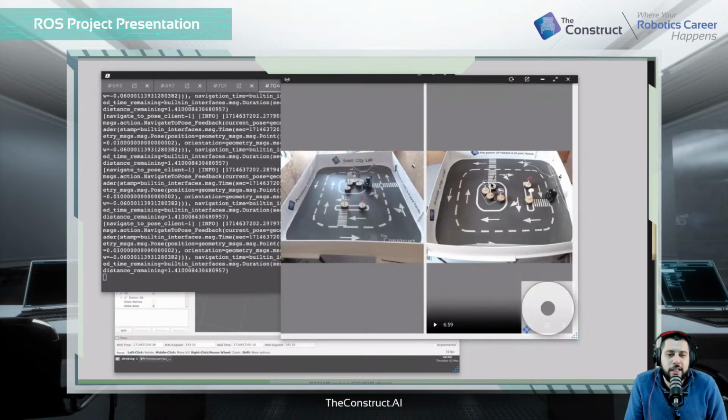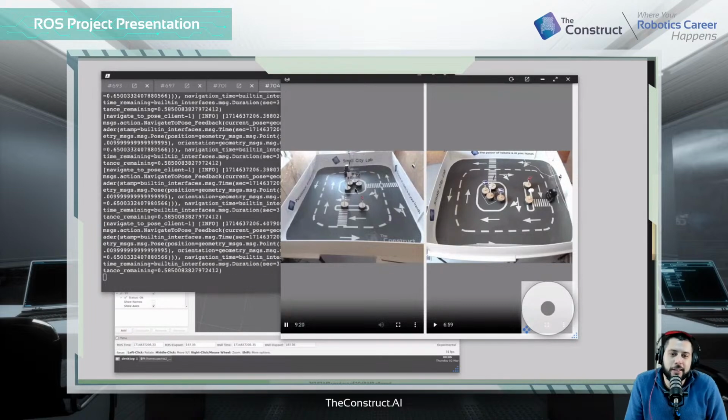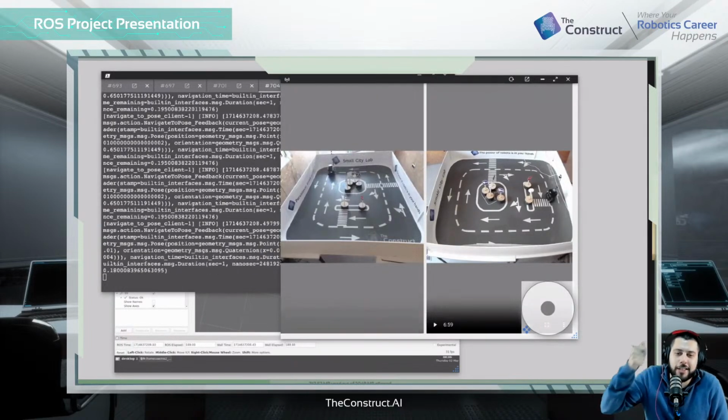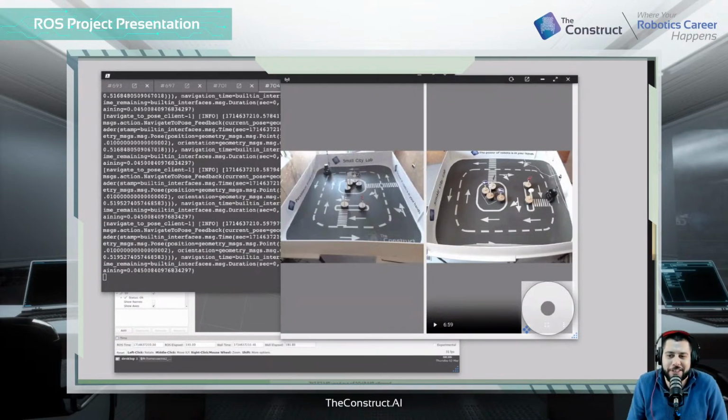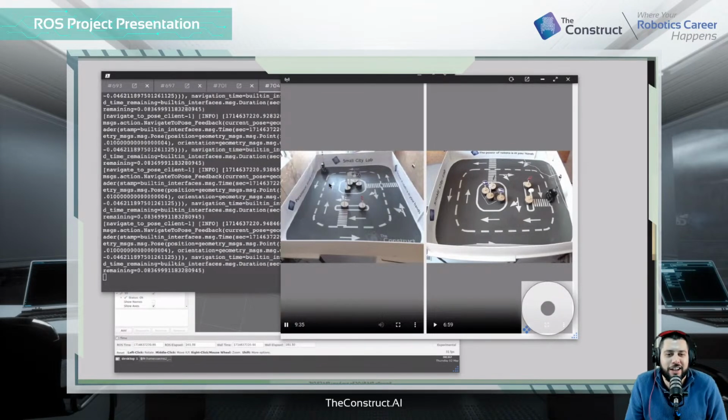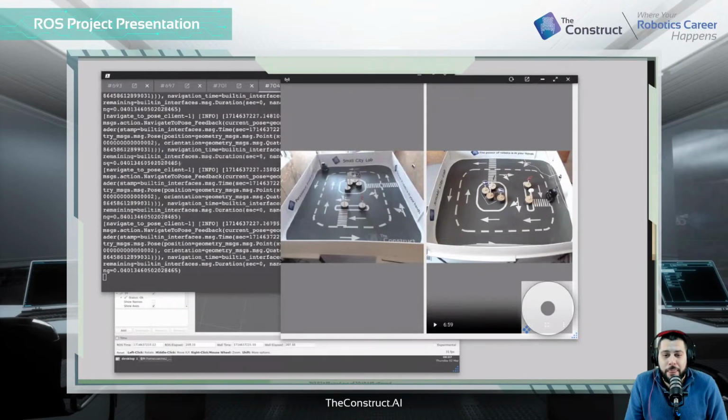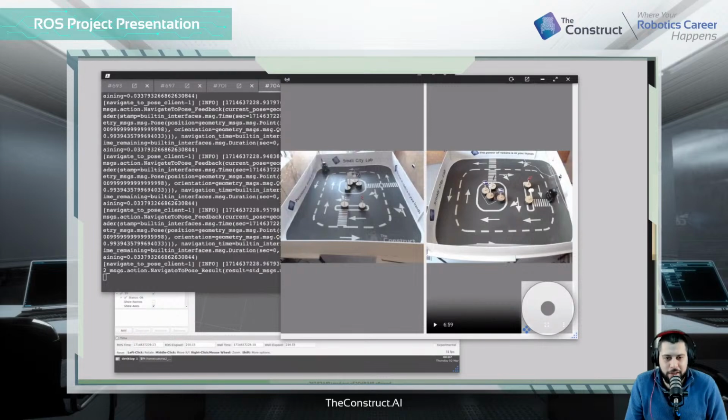And then we can see, that was very close. Very close. That's probably because it's only seeing the stick of the obstacle, it's not seeing the base of it. Oh, right, because the laser is a bit up. Right. Initially I thought that was due to the robot radius definition in the cost map, which I'll explain in a bit. So that was one of the challenges for me.